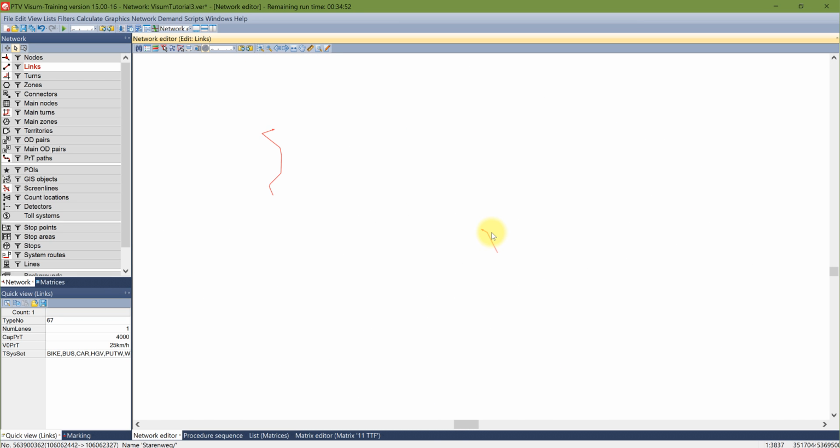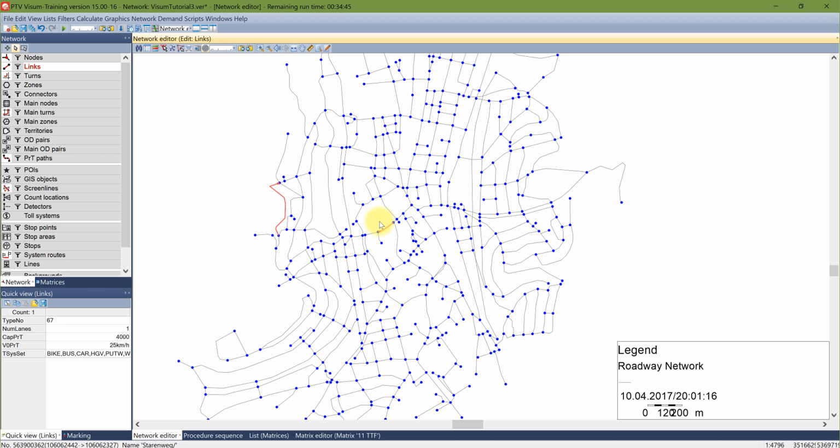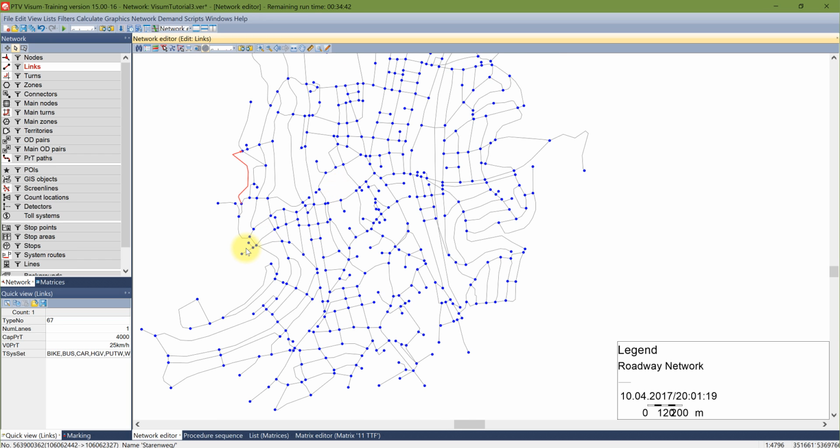The next thing that I want to talk about is shapefiles. Shapefiles are very commonly used in GIS. They could be points, polygons, and we can save data inside them as tables. So for example, if I have zones, I can save population, employment data, land use data inside them, and they are very helpful and useful to show some graphic display or to use it for different tasks.